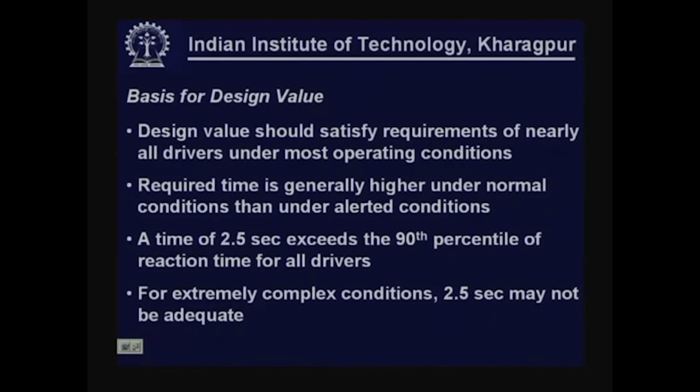One can justify that: if the 2.5 second value is taken, then it exceeds the 90th percentile of reaction time for all drivers. So, a 2.5 second reaction time is generally accepted for design purposes.